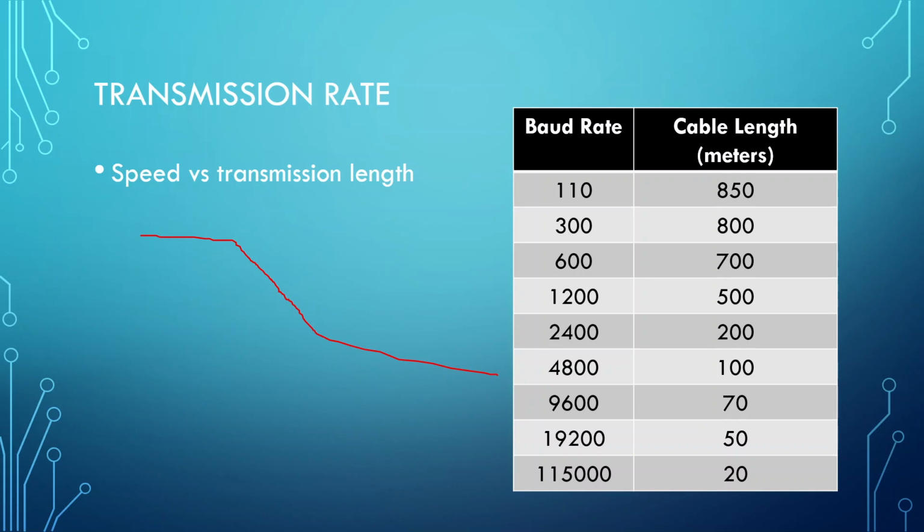Because of that transition period, and that capacitance getting larger with longer wires, we can't take a reading as often. If we took a reading right here, it'd be in that gray zone, and we'd be going, what does that mean? So we'd have scrambled data is what it comes down to. So length is really important here when it comes to your baud rate.